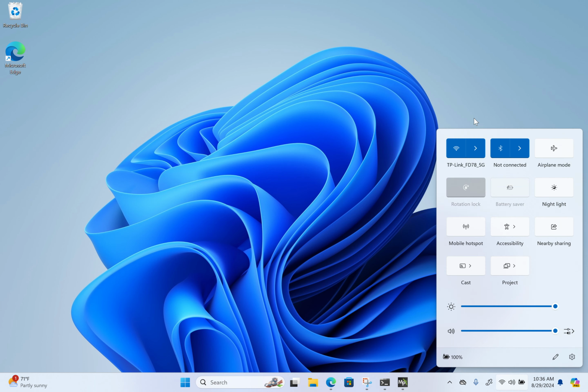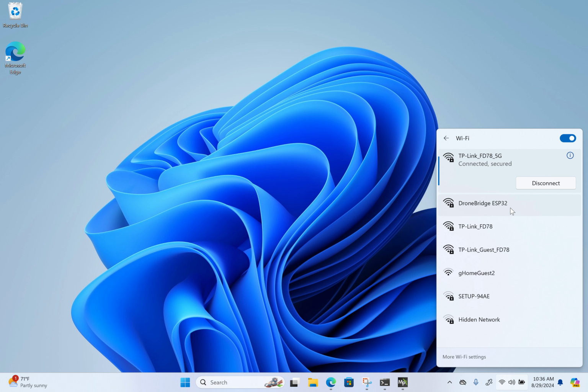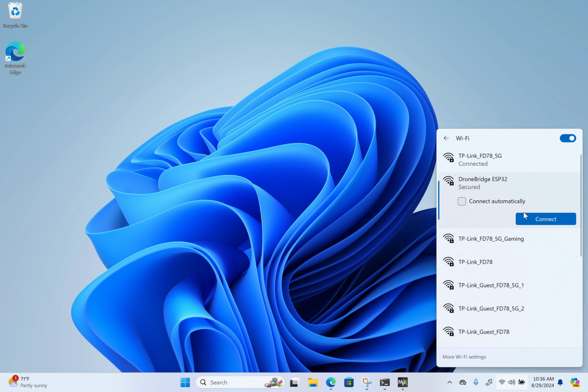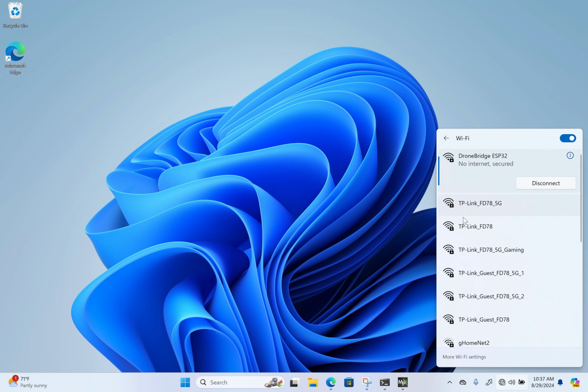So you're going to have to connect to the Dronebridge hotspot for Mission Planner to work. Click connect. And Mission Planner will actually automatically detect the incoming data stream on the UDP port and connect. If all goes well, let's see. And when Windows connects to the local hotspot, it worries because there's no internet connectivity. So it takes a while to check network requirements. We don't need internet connection. We just want to connect to the drone. So hopefully that will work.